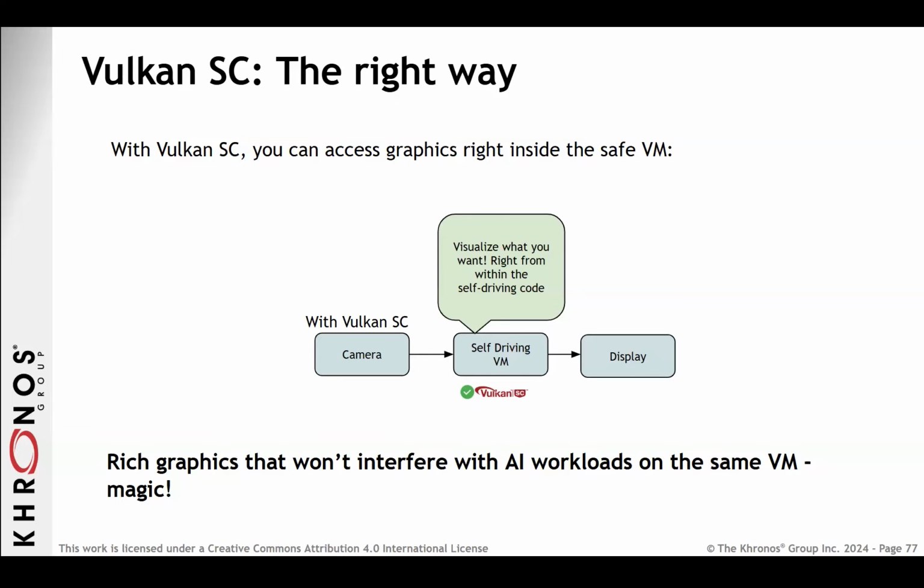You've definitely seen stalls on desktop apps when you hit a new area and a bunch of shaders load, or even worse, if you've seen this happen in embedded apps. It's very difficult to predict when the GPU will decide to allocate memory or when a shader compilation is going to start in GL or Vulkan. So in Vulkan SC, we remove these from the runtime.